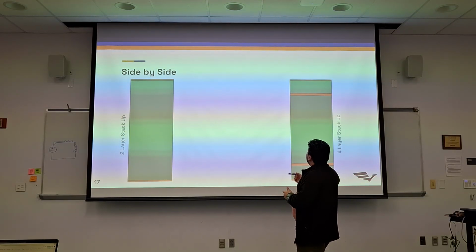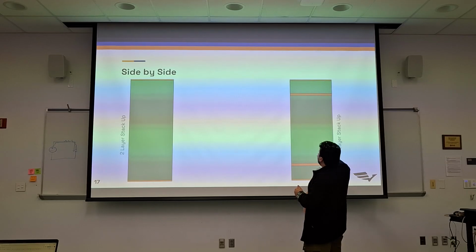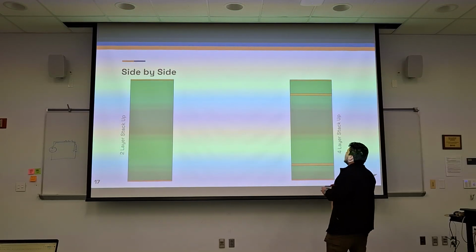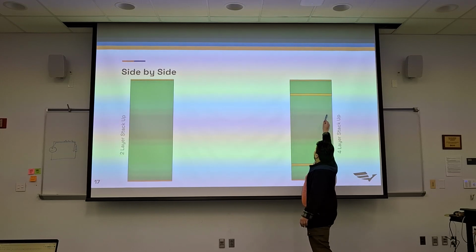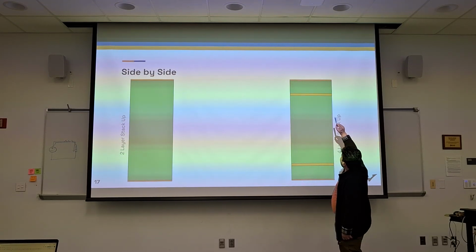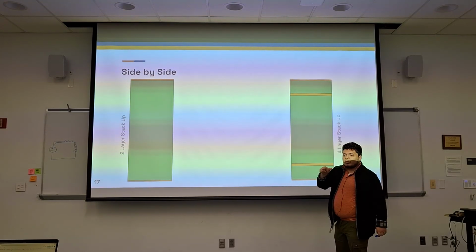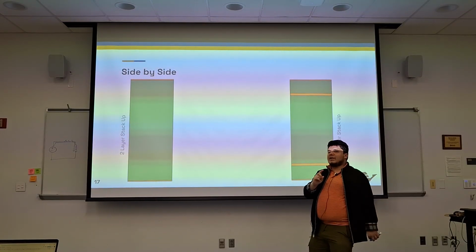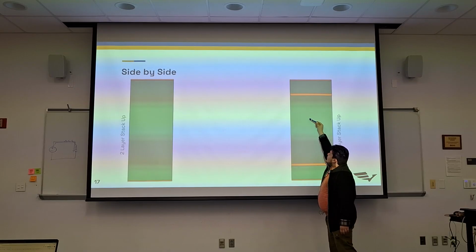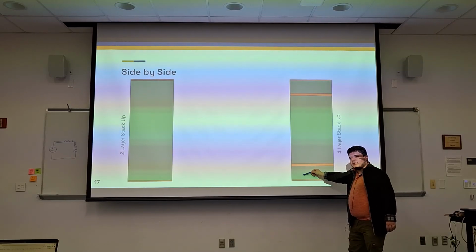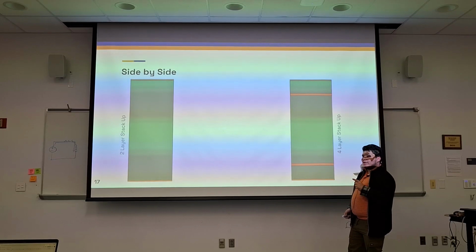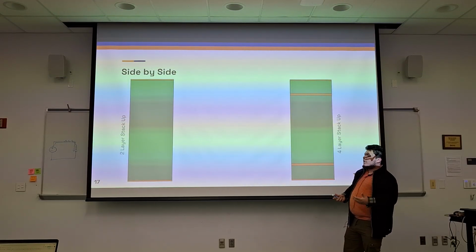And so if we had more layers even, so if we had a 6-layer stack up, right? And if we had our signals, give or take here or here, going from 1 to 3 is a nice short loop, right? Your signal doesn't have to travel as much, but there's a caveat. And that caveat is you still have a plated hole that goes all the way down the board. And that can be a problem because now you've created an antenna, right? And so there's pros and cons.